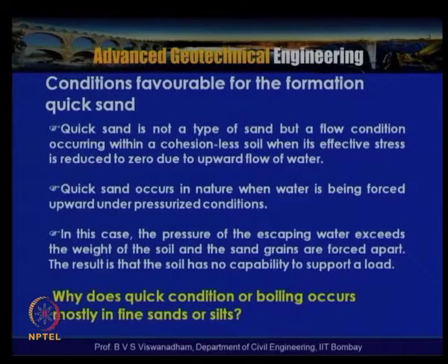What we discussed in the previous lecture is about the quicksand condition. We said that quicksand is not a type of sand, but a flow condition occurring within a cohesionless soil when its effective stress is reduced to 0 due to upward flow of water.